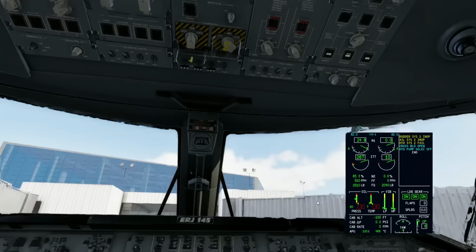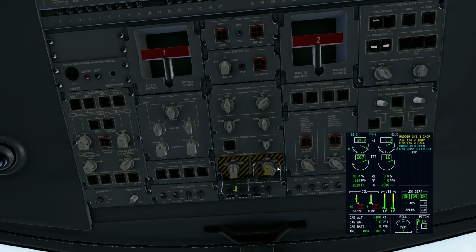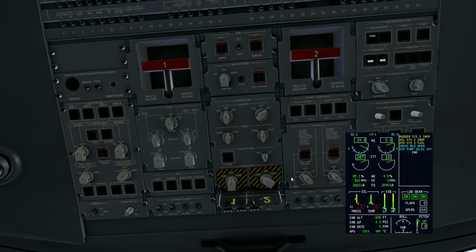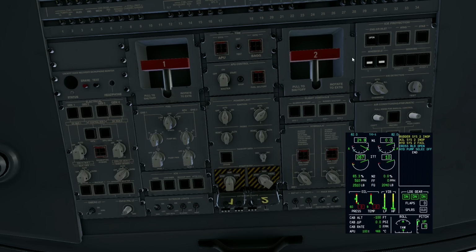And that's a good start on engine 1. Now notice our takeoff data still hasn't been taken. It's still not accepted, it's still not matching what we've asked for. Let's go ahead and start the second engine, and that'll get both FADECs understanding. Before I do that, notice that engine 1 has opened its engine air inlet valve. Because the valves are operated by engine air, we need the engine actually running before the valve opens. So that's an open indication on engine 1.